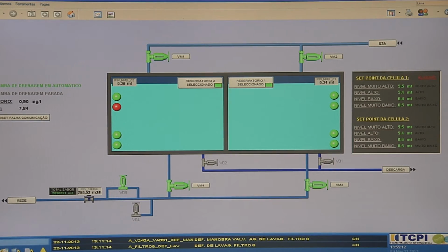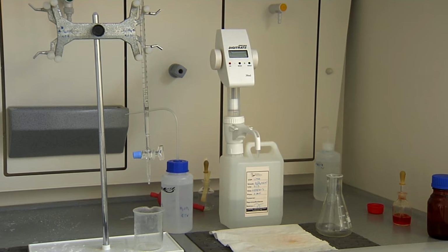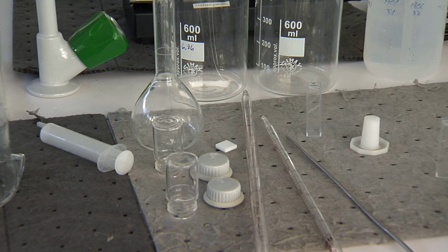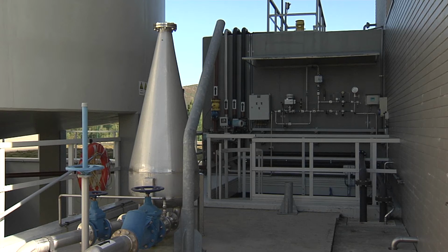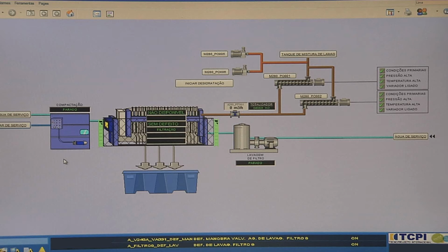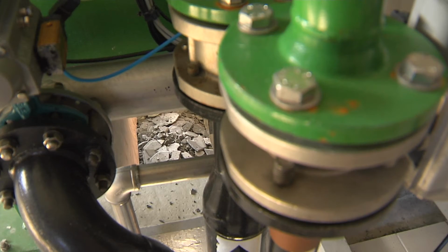Disinfection is performed between the tank and the treated water reservoir by adding chlorine gas. Subsequently, lime water is added for pH tuning. Sludges from filter washing are sent to the settlement tank and then to a gravity thickener. Thickened sludges go to the mixing tank, which also receives floated sludges and insoluble solids from lime water production. Mixed sludge is sent to the membrane press filter for dewatering.